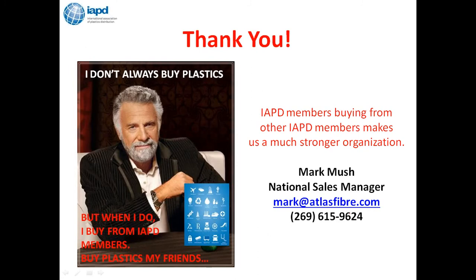And again, these are okay for outside applications, in general. It's just to take them all as a blanket statement. But G10, the glass grades, probably are going to weather a whole lot better than a phenolic grade, whether it be paper, linen, or canvas outdoors. But again, they're not UV stabilized.